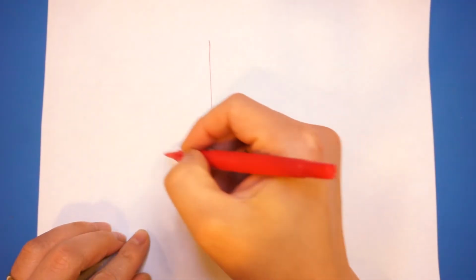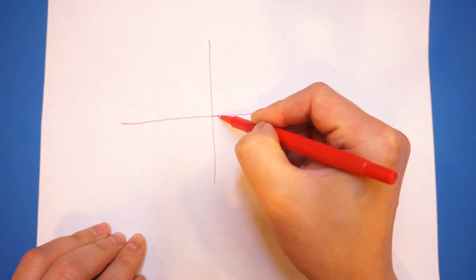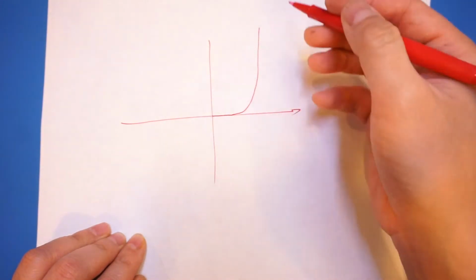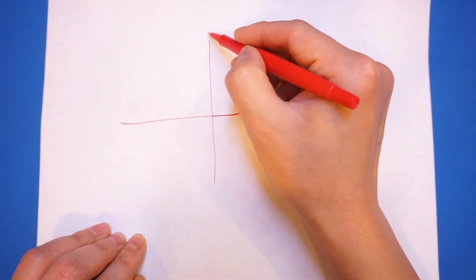The current flowing through any diode is a continuous function with respect to the voltage applied, whether it's forward biasing or reverse biasing. And we're all familiar with a typical diode's IV curve, which I will show here. So for your typical diode, the IV curve can be drawn like this. Basically, in the forward region, we would observe a sudden current rise after the voltage. So here is our voltage, here is our current.